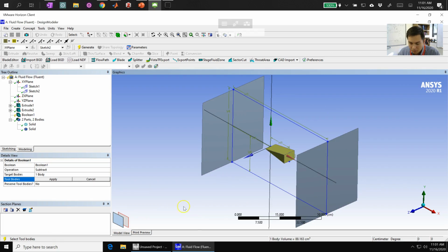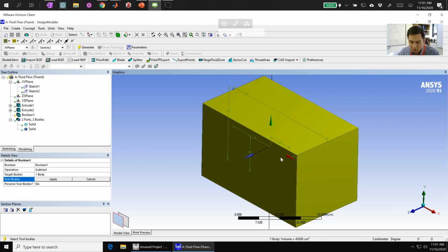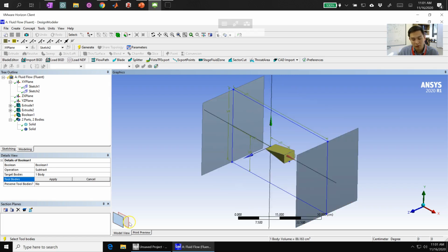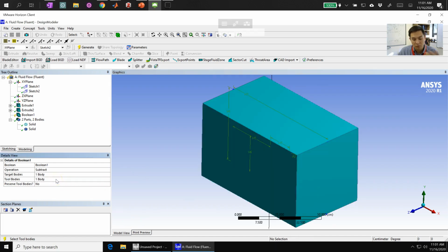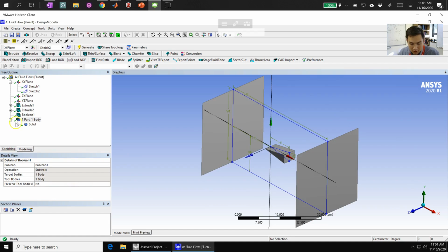our wedge. So you'll notice if I click somewhere on the body or in the domain, in the bottom left corner here, you'll see that there are a couple options. So the current option is highlighted in red, but we can go to a different layer or a layer below, which in our case we are wanting to do. So we can click on the next layer, which would be the wedge itself, and that would be the tool that we want to apply. Okay, we can go ahead and hit generate, and our Boolean has properly completed.